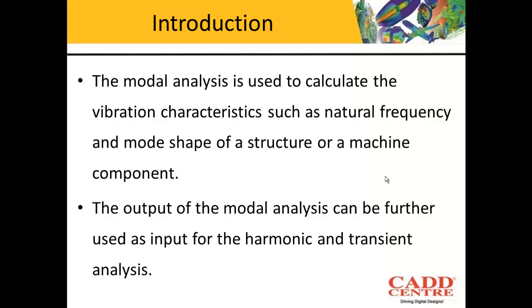The modal analysis is used to calculate the vibrations such as the natural frequency of the system, and at that particular natural frequency, what is the mode shape of the system that we need to calculate using this type of analysis. Basically, the modal analysis that we are going to perform will be used to calculate the natural frequencies and the corresponding mode shape of the structure or the machine component.